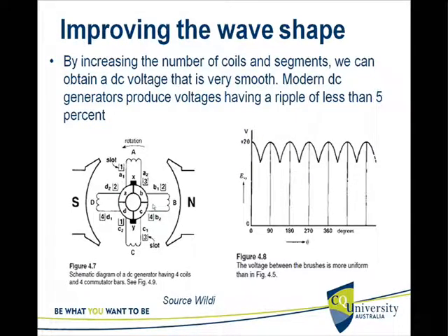This is what we do. Instead of having just 2 poles, you could make it 4. So now two windings perpendicular to each other, and 2 sets of brushes, or 4 brushes. Each winding is connected to 2 of these brushes. Still, the brushes that take this voltage signal out are in this vertical plane, which is the magnetically 0 position.